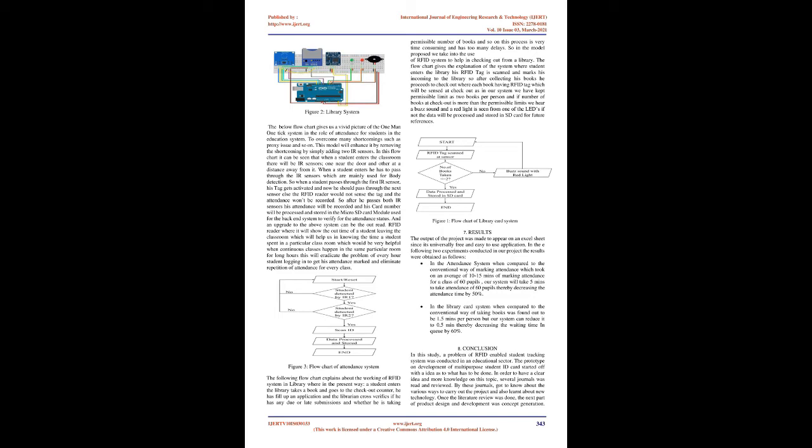Pins 6 and 7 have been connected with the LED lights. And lastly, from the digital I/O ports there are pins from 9 to 13 making way to the RFID reader, RFID RC522. This is used to sense the tag from the student's ID card during check-in and even during checkout, where it will transfer the details to the micro SD card module for data processing and storage.